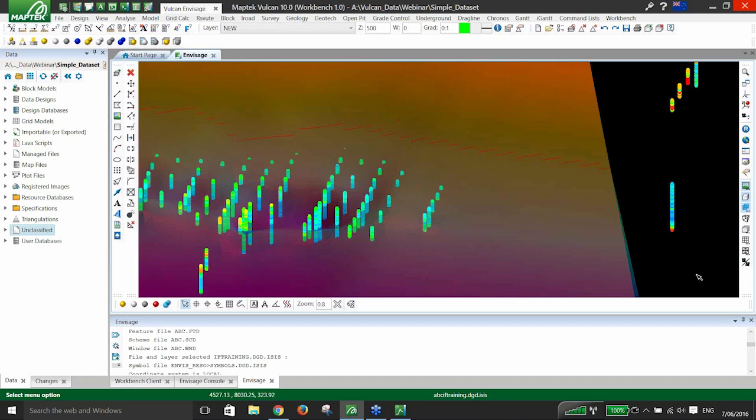And I'll have a last-minute question, which I'll answer, which has come in, that a customer would like to be able to use non-composited data in the analyzer. And currently, the data analyzer supports compositing databases. So the geological databases will be in Vulcan 10.1, just your standard ones. But I guess you can do a straight composite, which converts the geological database into the Vulcan compositing database file, and then has that ready so that you're not doing anything with your sample intervals.